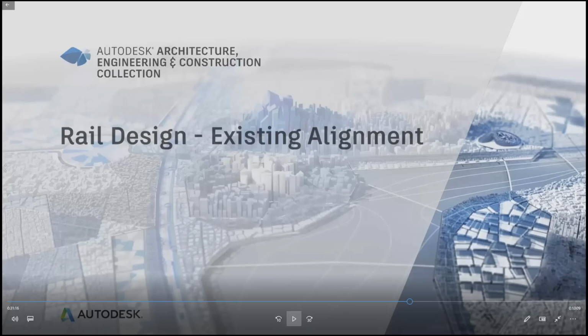Another question is, are multiple corridors in one section stable? They are, and you don't have to run multiple corridors per se, but multiple baselines is what you can do. And that's the beautiful thing about the way that the corridor model is set up. I'll show you in this next model, we've got, actually, I think in this case we had 5 sub-tracks, a storage track, and then 2 main lines. So we've got 7 or 8 different tracks and different alignments in one corridor, and it is stable.